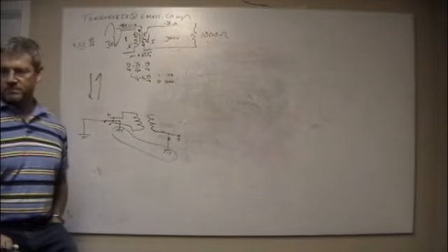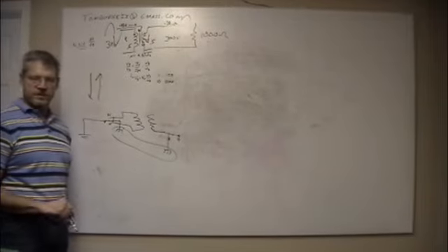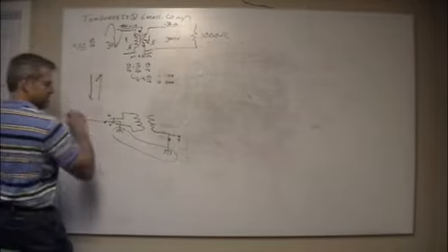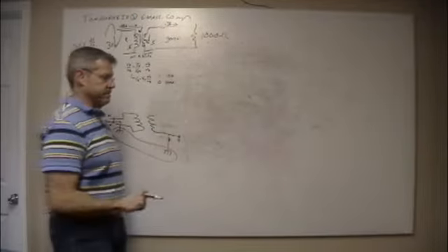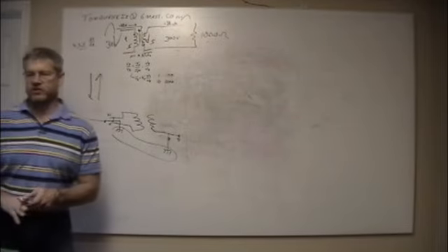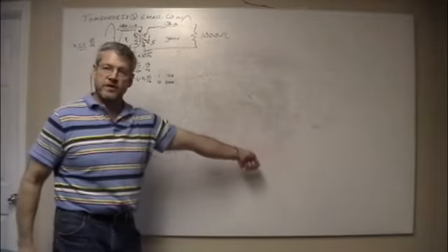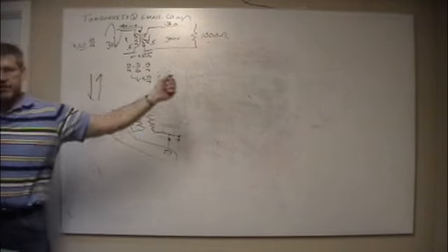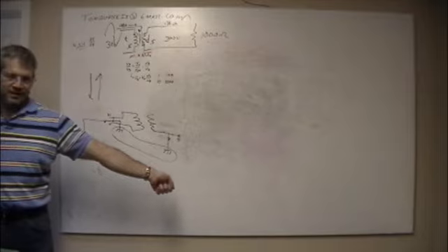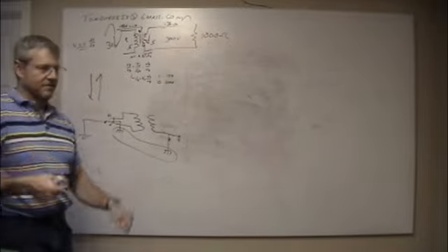Like why? Ground loops. You don't want signals here running out and coming out here and polluting things over here, and you get weird, goofy things happen because current always has to get back to where it came from, and if it finds another way to get here, and then it has to go all the way back here, everything quits working. Ground loops are a pain in the ass to troubleshoot because you don't know. You got to start turning things off. Click. Yeah, that thing's still not working. Okay, we'll turn that back on and come over here and turn this one off. No, it's still not working. Fuck. Now we'll turn both of them off. Oh, okay, now it works. All right. Somehow current's going away and coming back in through these two things and getting noise on it.